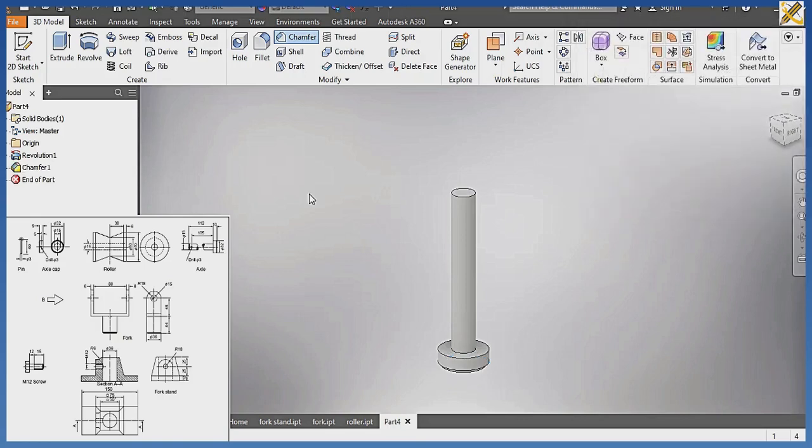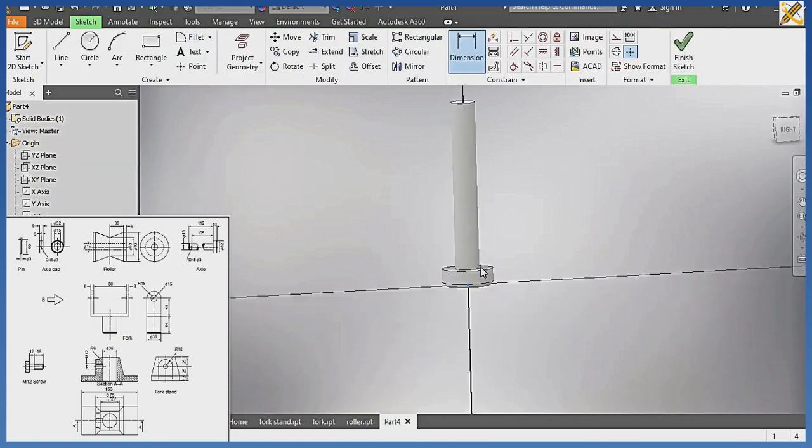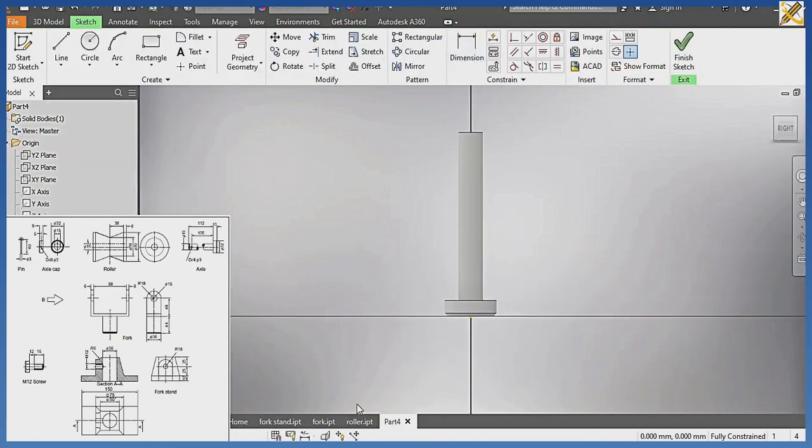Then what? OK. So I'm going to come here, origin. I'm going to pick YZ plane in that order. Create a new sketch like that. Okay, clicking on my slice graphics or F7 on your computer system.